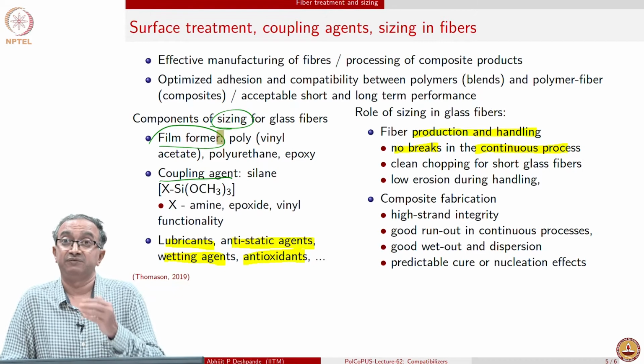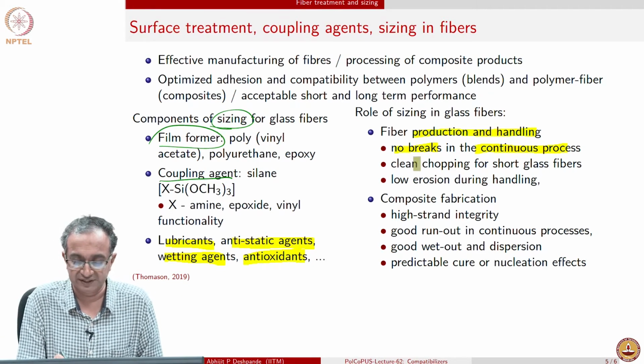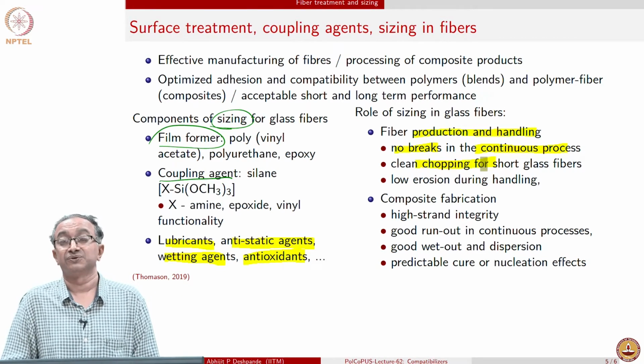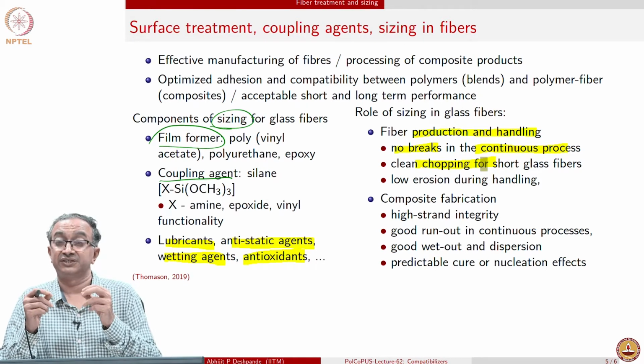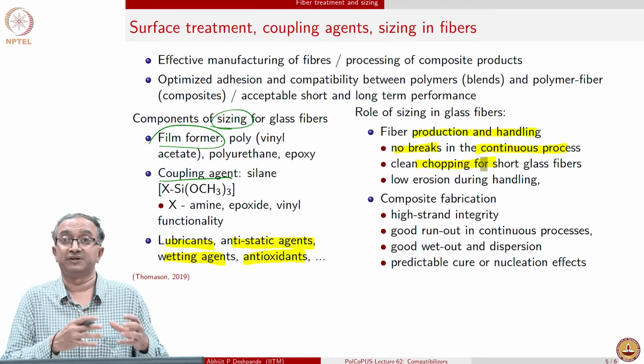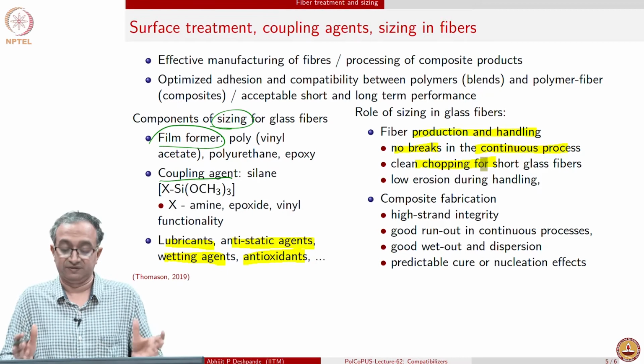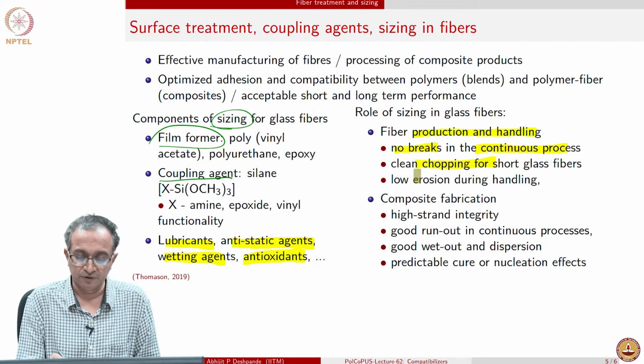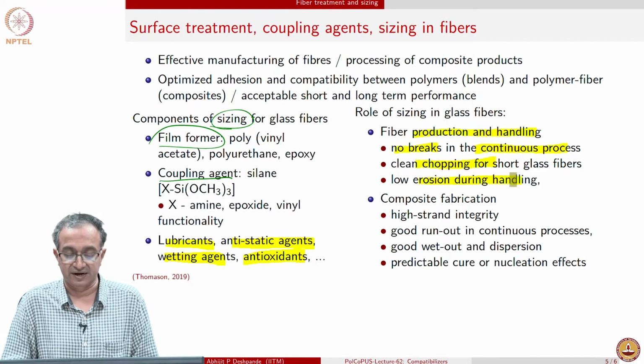Many times we will use short glass fibers. In that case, the chopping should be clean, so that again the adhesion between the polymer and the fiber is good if there are such surfaces, and also we can minimize the erosion during handling.